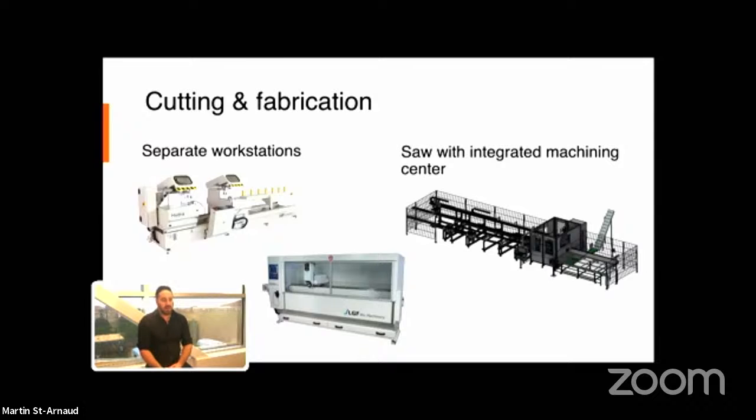In there, if you're looking at sashes, you're going to be able to do all your hardware pre-location. The only thing you're not going to be able to do in one of those would be drainage if you're looking at casement sashes. But if you're looking at hung and sliders, you're going to be able to do even up to your drainage as well. If you're looking at working with frames, you're going to be able to do, again, everything but drainage on those.